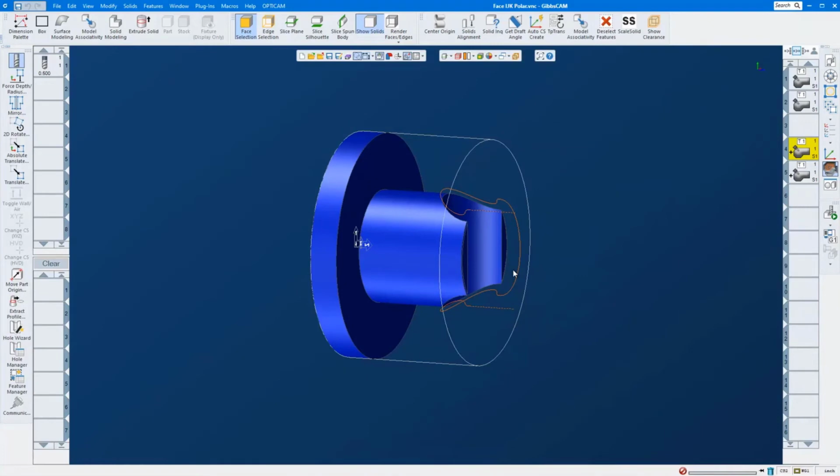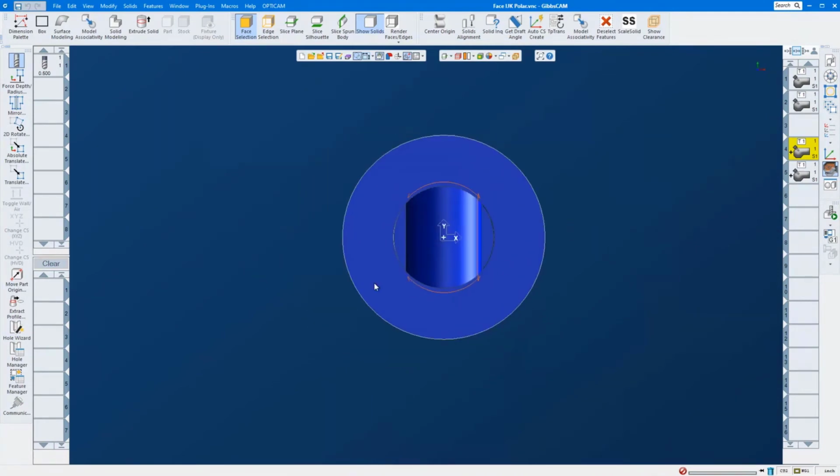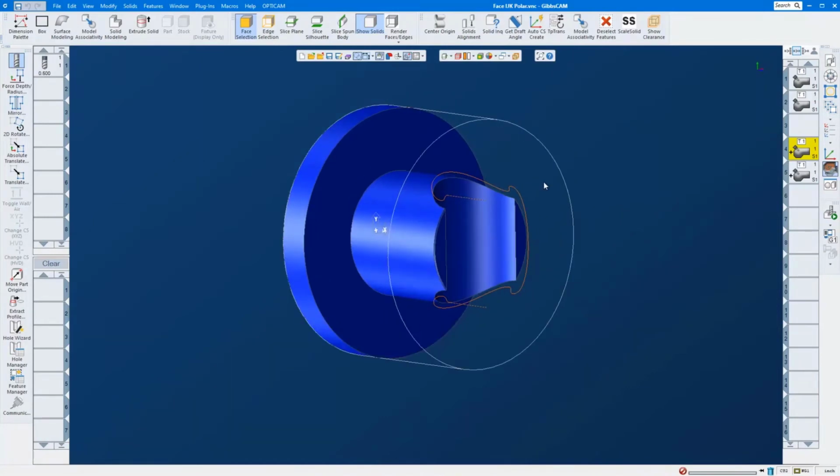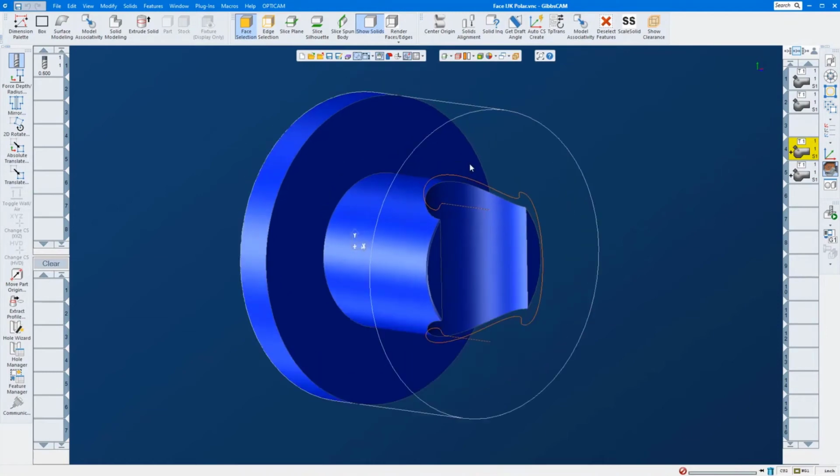All right, so if you imagine a lathe with live tooling and a C-axis, the tool always has to be pointing towards that rotary axis. So this will work on lathes and mills, but more times than not, this is used on a lathe that doesn't have a y-axis.